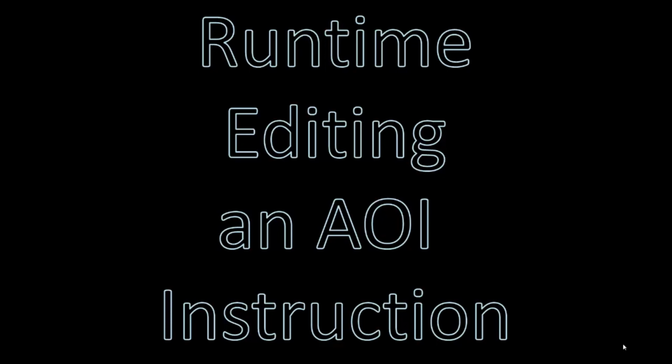So it's not a matter of anything other than you cannot edit it in runtime. When I say runtime, I also mean in the program mode. Add-on instructions can only be edited offline. Now there's a good reason for this. And it doesn't even matter what the reason is, it's just the way it is.